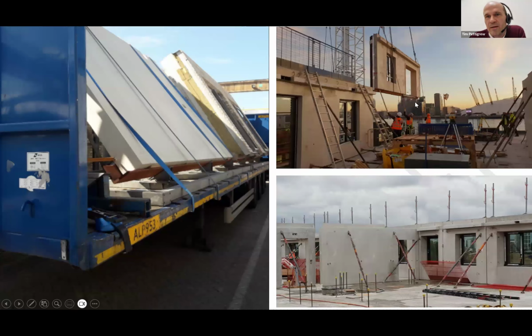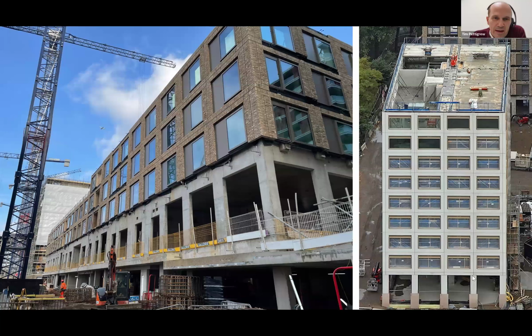Here's the panel arriving. One crane operator drops it in, a couple of props get attached, they walk away, get the next panel and get going for the rest of the facade. So literally a whole floor plate is put up in 1 week. Again, this is the reinforced concrete traditional base, and we built off that, and these were picked up on the slab edges and built very quickly.